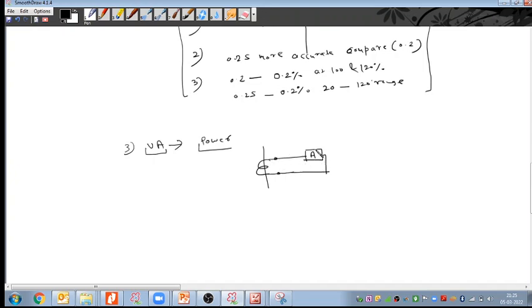Here we also have interconnecting cables, and the cable has some resistance, and it connects to the external meters. So this CT core must be suitably selected so that it can produce the required power to flow the current.